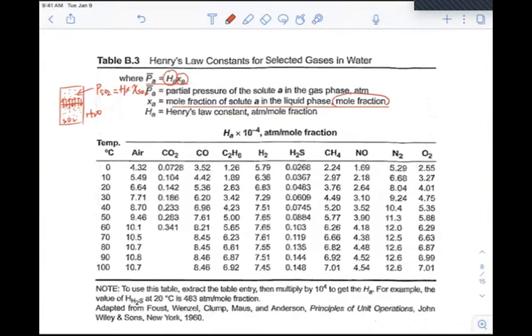For example, let's say that you have 1% sulfur dioxide in the gas phase. It's going to achieve a certain equilibrium here. For example, with that you achieve a molar ratio of 1 ppm of the sulfur dioxide in the liquid. Then if you increase this partial pressure, or increase the percentage of sulfur dioxide to 2%, basically you double the amount of sulfur dioxide in the gas. Then in the liquid, the sulfur dioxide concentration, or the molar ratio, is going to automatically change to 2 ppm. So you have this linear correlation here. What will determine this linear relationship is this constant here, and this constant is called the Henry's law constant.